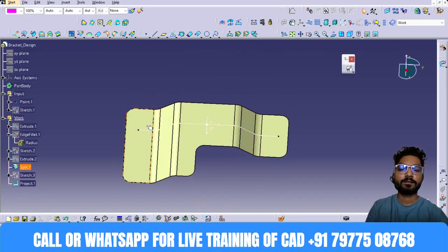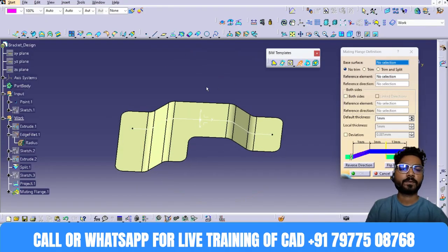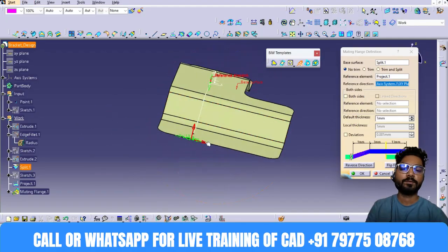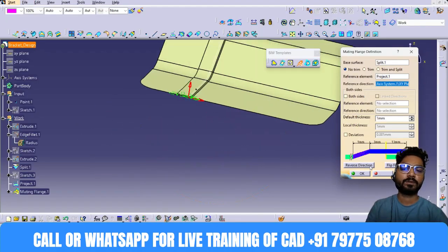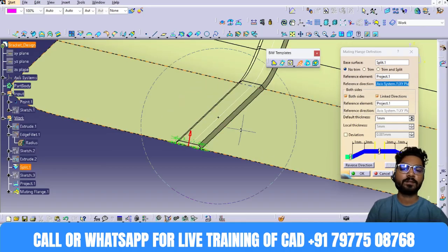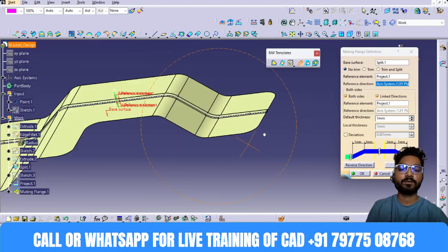Now next thing is, here I want to generate a mating flange. So you can use the BRW templates toolbar. From the BRW templates you will get this command, mating flange. So you can select mating flange. Here base surface is this, reference element is this line, and reference direction is XY direction. If I preview, you can see the flange is created, but it is being created on one side like this. I want both sides the same, so click on the both side option. So you are getting the flange completely throughout the part.